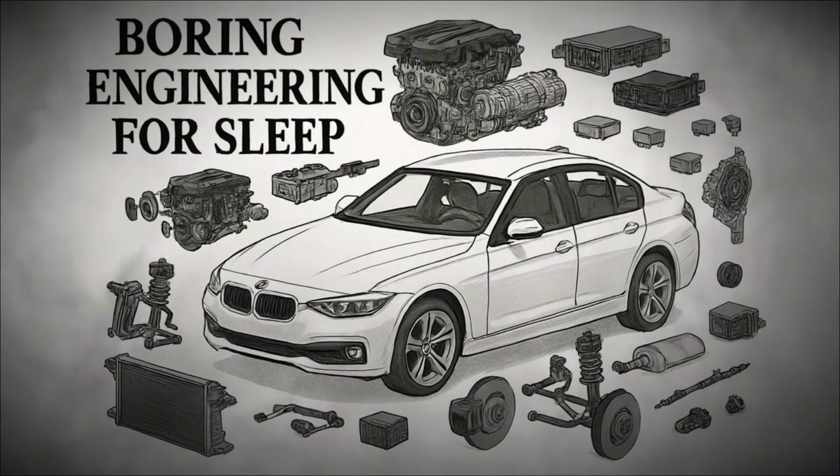The clutch is one of the most important components in the connection between the engine and the transmission, and its purpose is to allow the driver to smoothly engage and disengage power so that gears can be changed and the car can start moving without sudden shocks. In its simplest form, the clutch is a mechanical device that connects two rotating shafts, one from the engine and one leading to the gearbox, and allows them to be temporarily separated when needed.